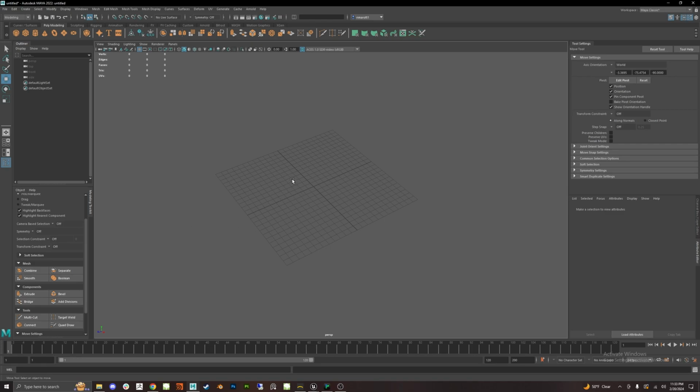If you want a smoother experience, and sometimes you have to do this based on where your center of orbit is, I'm holding down Alt again, and I'm holding down the right mouse button for a smoother experience, and I can continuously zoom in, continuously zoom out. The reason why that is useful is because when I'm doing this, it starts to slow down the closer I get to where it thinks my center of orbit is, or the more I zoom out, it starts to slow down again, proportional to how far away that orbit is.